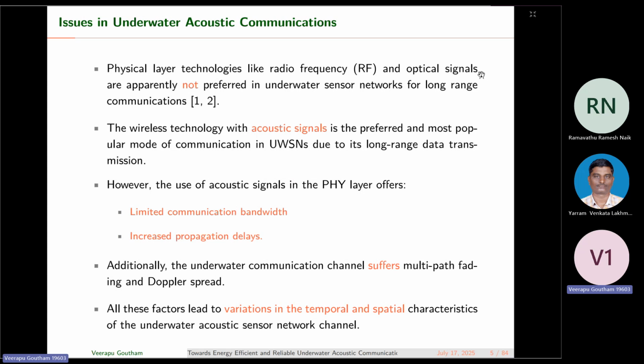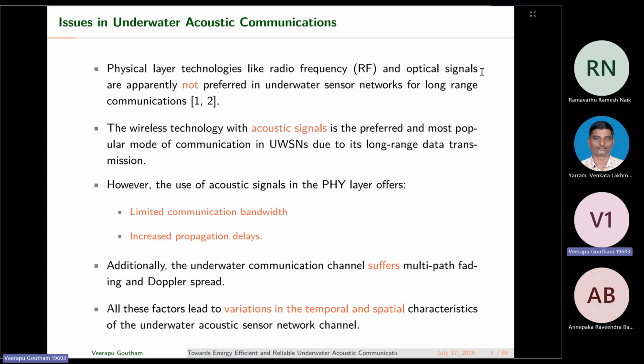Then what are the issues available in underwater acoustic communications? The bandwidth we will get in underwater acoustic communications is very limited because these frequencies are in a few kilohertz. Due to that, the bandwidth we will get is very few hertz only. Due to that, what is happening? The data rate is limited. Due to the limited communication bandwidth, the achievable data rate also is very limited.